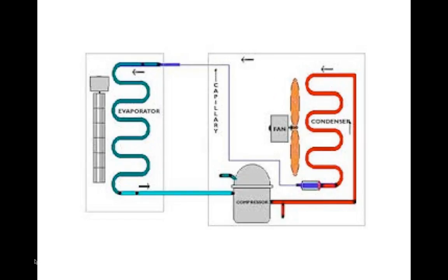And then you blow air into the home, and then it's got a little vent usually on the bottom, pulls air back over, so you're continually recirculating air over that evaporative coil. Well, the problem is that now you've evaporated that Freon in the cooling process. You've turned it into a gas. So if you go down on the bottom, you see that light blue color that goes back to the compressor. That Freon gas, hot Freon gas, goes back to the compressor.